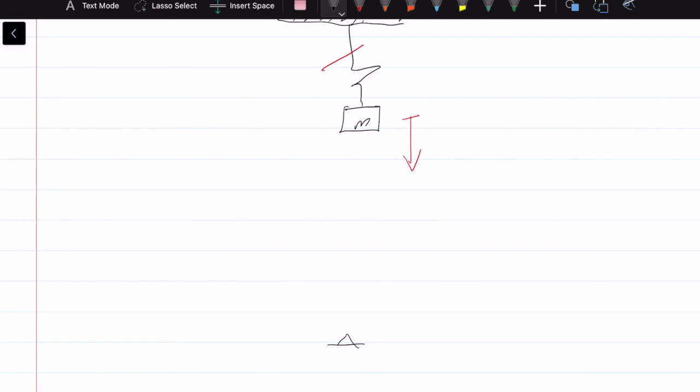So if we have an inverted pendulum and we've got, let's say, a point mass right here, and instead of a normal spring, we have a torsional spring, KT, and we've got a mass. If I cut this spring, absolutely nothing will happen because all the weight is acting straight down onto this rod. And therefore, when we do Newton's method, or any other method, in fact, we have to take into consideration this mass. This might not really make a lot of sense right now, but what's important is to understand whether a mass is in static equilibrium or not.